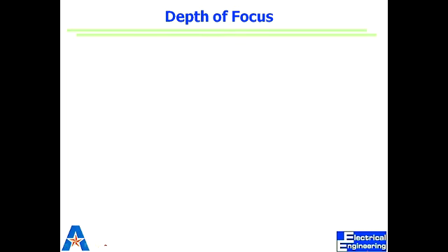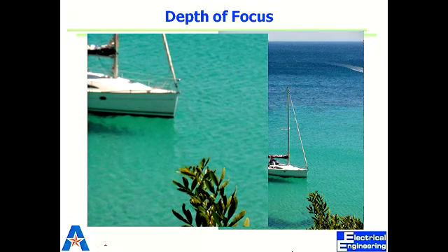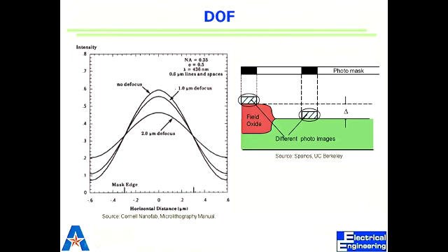So one of the things is, what is the largest numerical aperture you want to limit to, to still have reasonable depth of focus. So this is just to give an idea that one of them can be in focus, but others can go out of focus. So this is intensity and horizontal distance, and you are seeing defocusing. If you are not out of focus, you get this guy, but once you go out of focus, yes, you get the intensity to transfer, but then your pattern size is also going to increase in width. Right? Does it make sense?